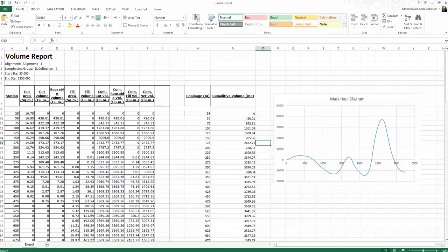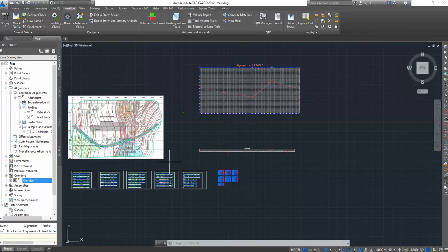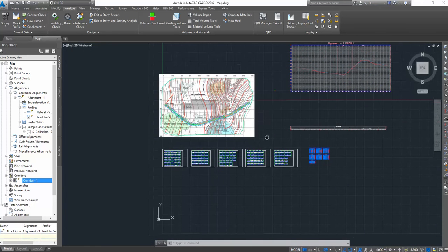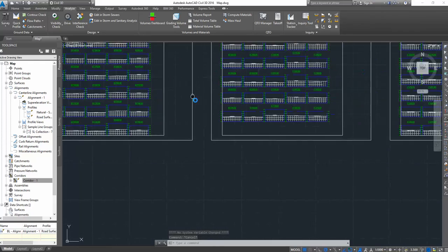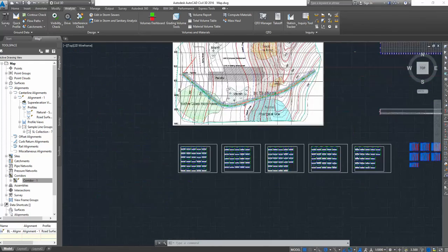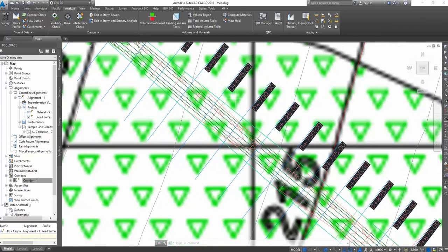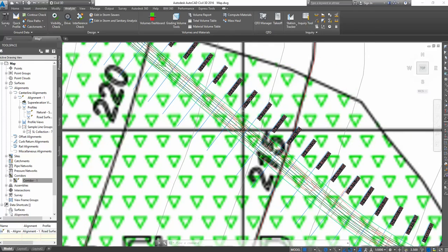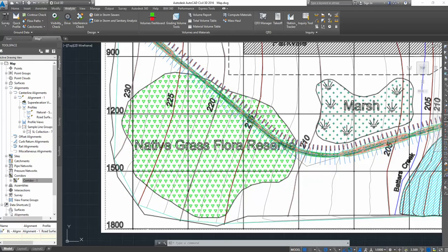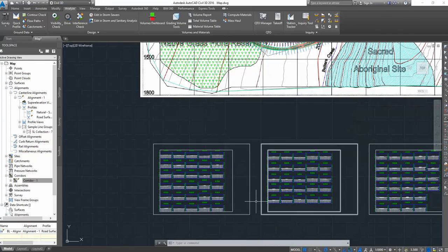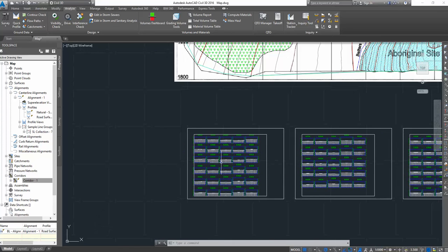That's okay. Come back to here. And this is done. The next thing you need to do, cross sections. So click escape again, come here, zoom. So let's say I want to do one at 700 because you need one in here, like of your 10 cross sections that you need hand scale drawings of.